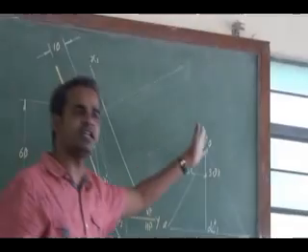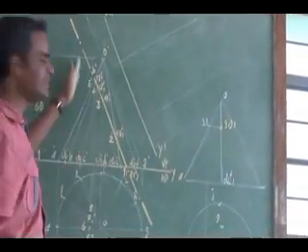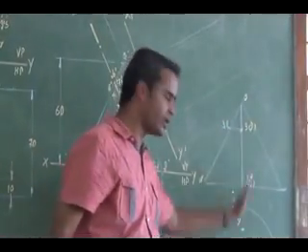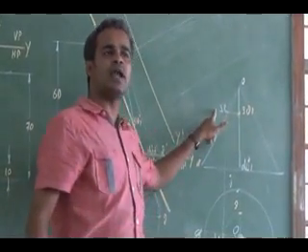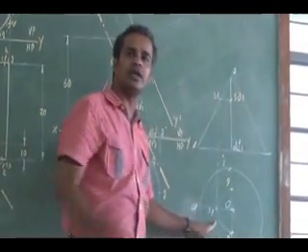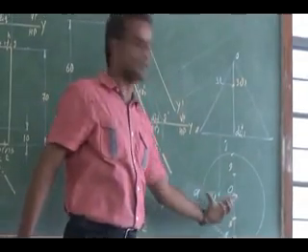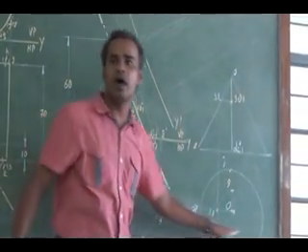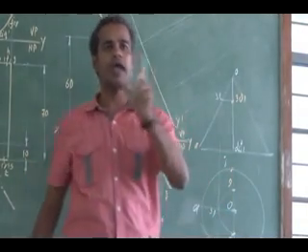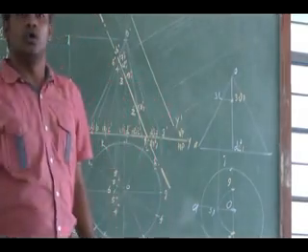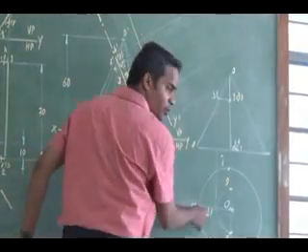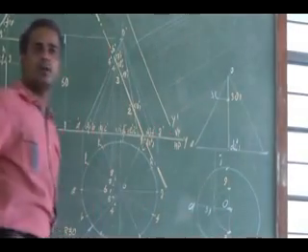If a point is on a slant generator, it can be projected directly to the top view. Since it is on a vertical projector, I have to transfer it to another extreme, slant projector. From there you measure the distance from the apex and mark it on the appropriate generator.